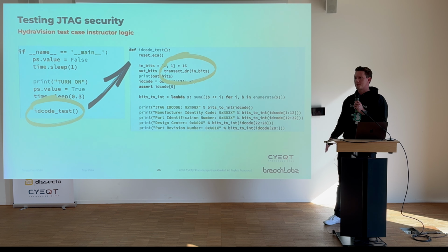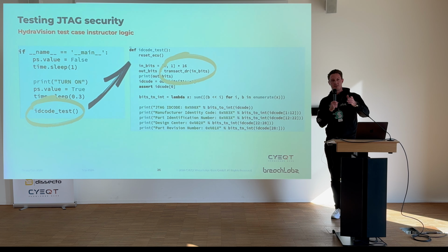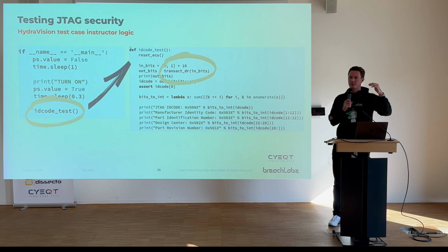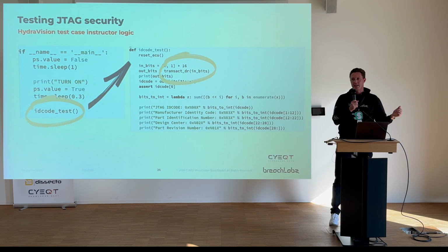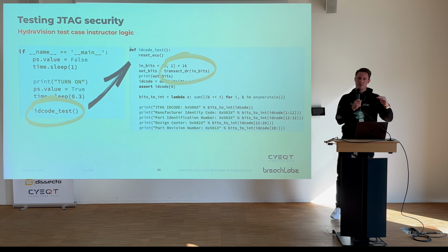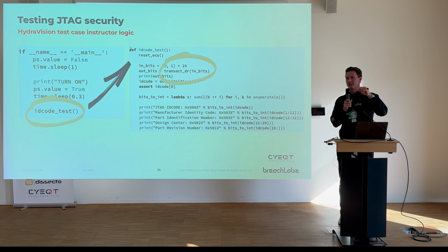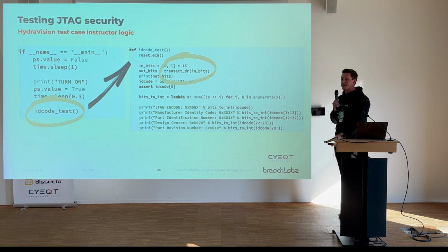It's a very similar approach. You basically do the exact same thing, right? You set all ones in your instruction register, then you set zeros in your data register, and push as many in as you possibly can in order to reset all of the different TAP controllers on the line. Then you push in a 1, and count the amount of clock cycles until the 1 comes out on the other side. This is how you determine the amount of TAP controllers. Any questions to that?